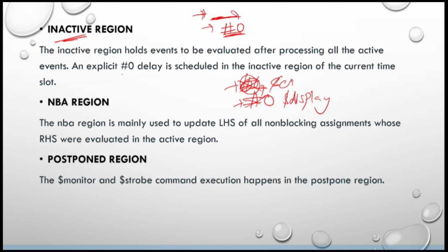Because this is the most frequently asked interview question, when any interviewer wants to trick you, they will give such questions like what is the difference between $display without delay and #0 $display. So what will be the difference? Actually, this is executed in the active region, and this is executed in the inactive region. There may not be much difference, but this is the major difference. So this is about the inactive region.